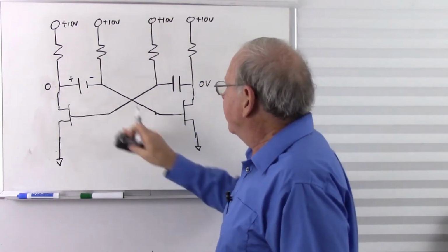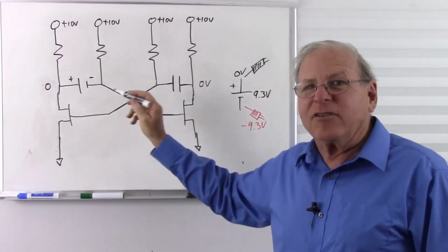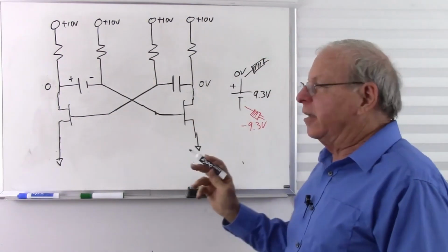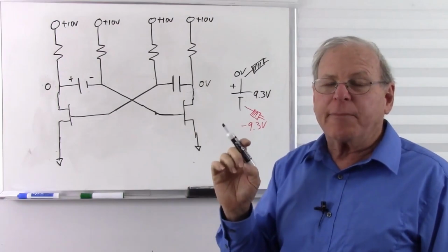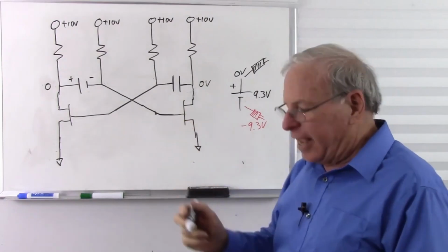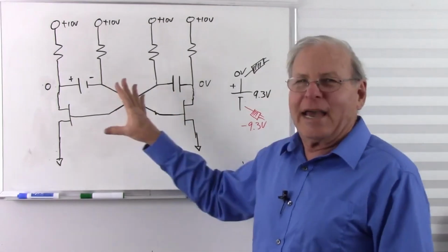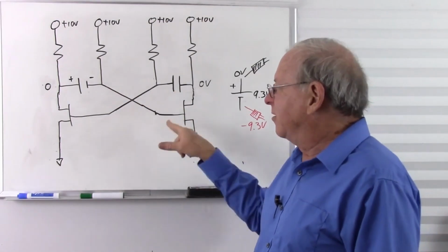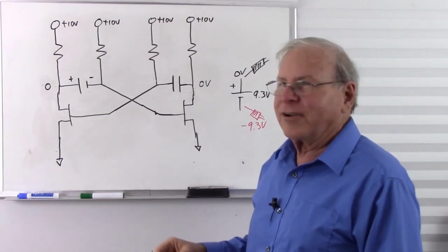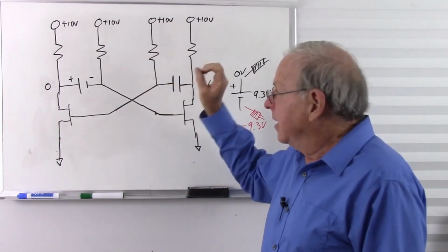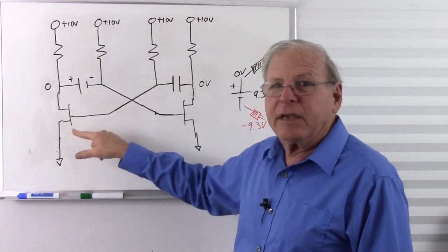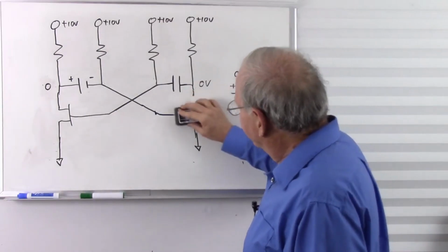We don't get that same disparity, and it's going to act exactly like it did with the relays again. So only if we use bipolar junction transistors do we get that negative voltage on the base of the transistor. So don't get confused about that. Oh yeah, Astable multivibrator, we get negative voltages at the gates of the transistors, not with FETs. That was all because of the nature of the base to emitter junction of the bipolar junction transistor.